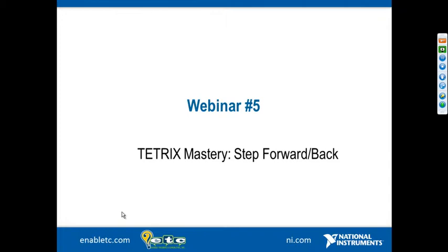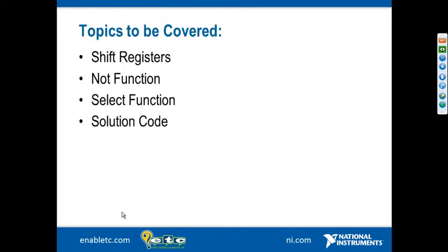In this webinar, we're going to cover a topic called step forward or step back. In a nutshell, it requires using a slightly more advanced programming concept which allows us to remember something from before in order to make a logical decision. The topics we're going to cover are shift registers, a Boolean function called the not function, another function called the select function, and then we're going to create some solution code and explain it to solve this step forward, step back problem.